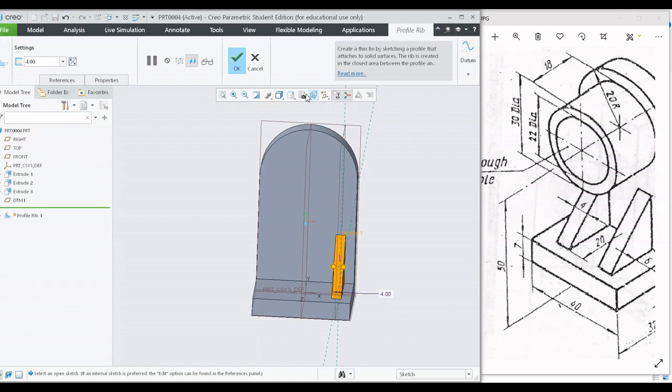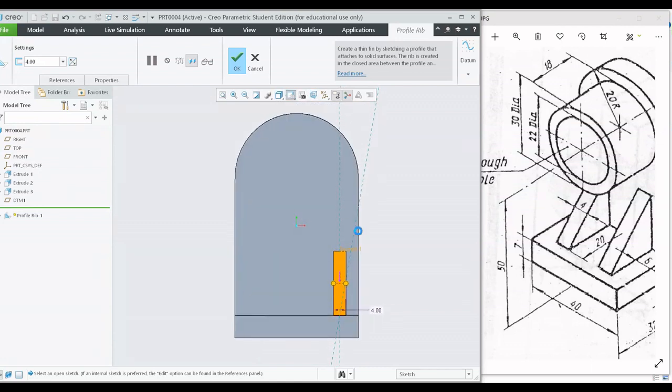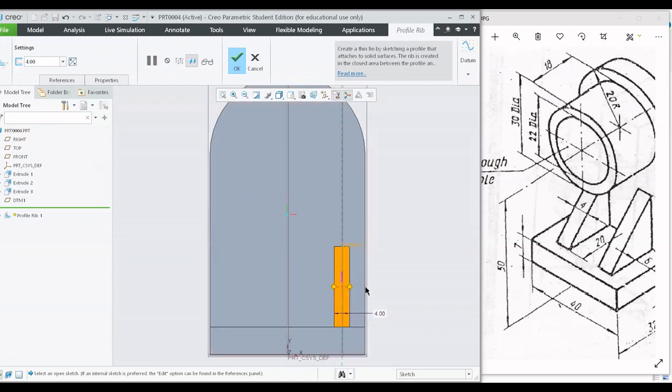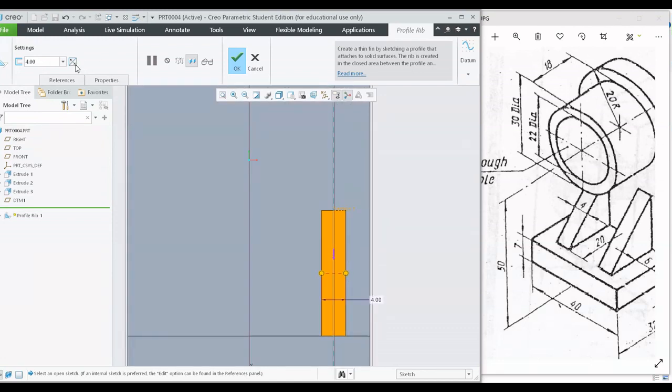I have changed it to 4. So this is the plane we have created. It need not be symmetric, it has to be on the other side because this distance is equal to 6 units. If I keep it symmetric, then this distance changes to around 6 minus 2, that is equal to 4 units. So this is inappropriate. Let me change it to this side.